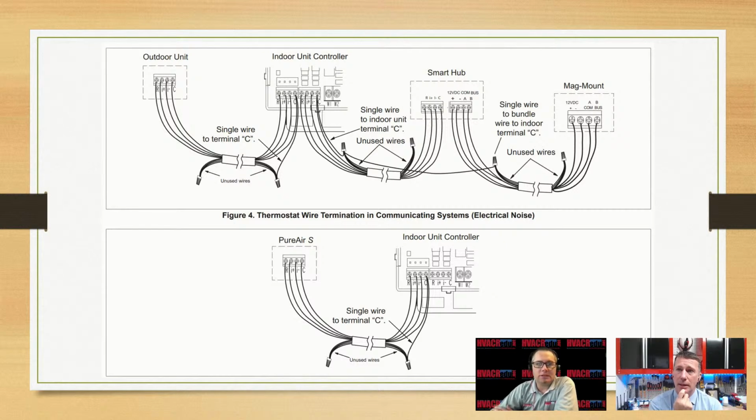Anyway, those wire nuts, for anybody who wants to tell us what's going on there, it looks like it's all going back to the indoor unit. Why would we do that? And then trace it down, you go to the outdoor unit, but hey, those extra unused wires are not hooked up to anything, but they go back to a common. Everything's going back to common at the indoor unit. Sounds like some kind of grounding to me.